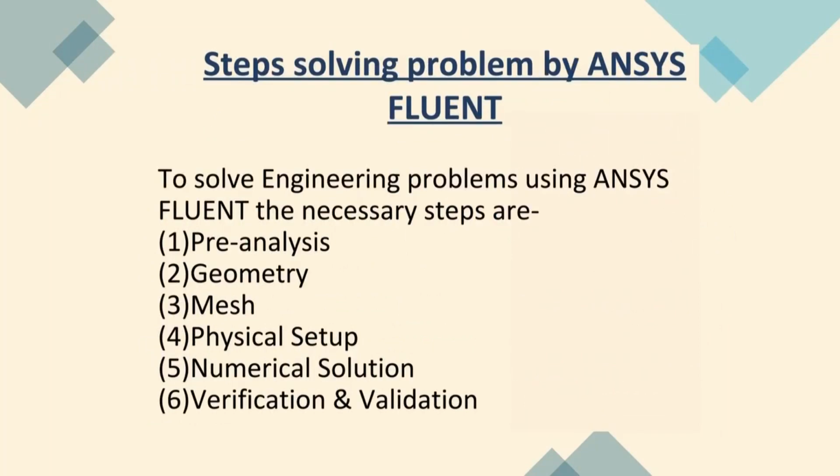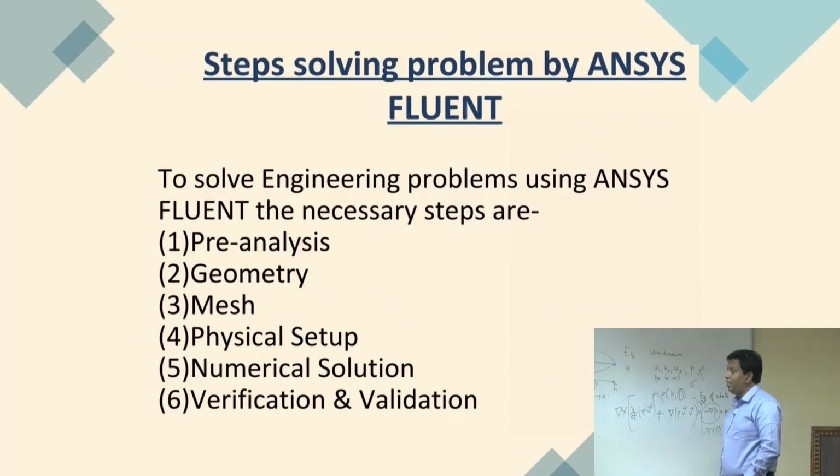Now the steps in Ansys Fluent, what steps we want to follow here. At first, the pre-analysis. As I said, what kind of problem you are going to solve, what could be the initial and the boundary conditions. If you have everything handy, then you create the geometry.